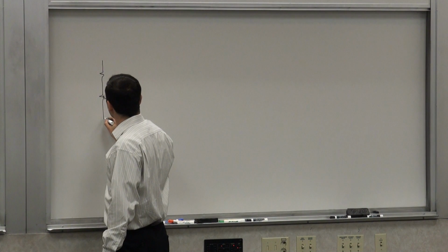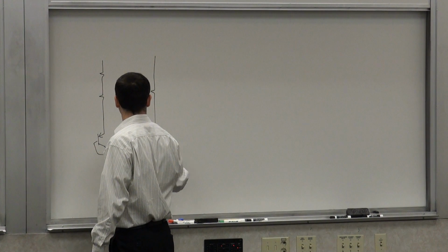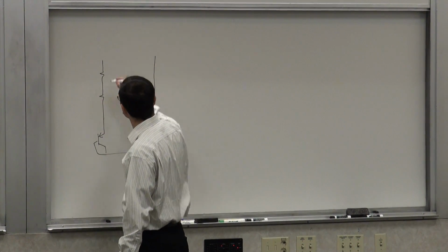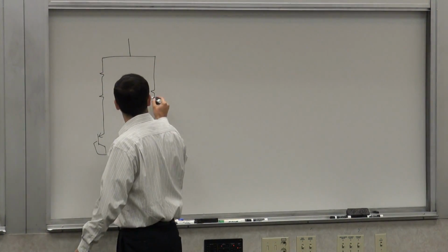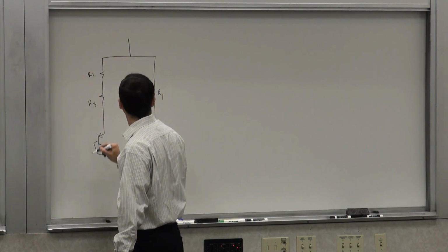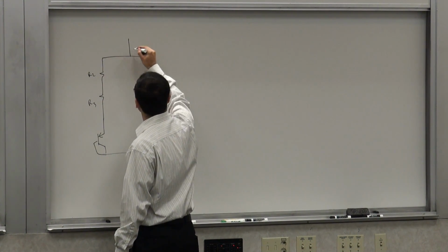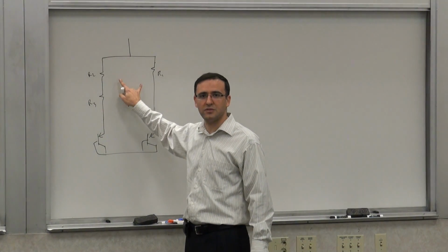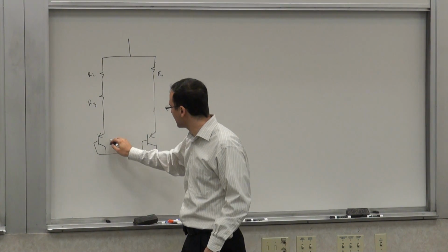So you take two VBEs and two resistors, connected transistors, and then you basically take this voltage. So let's call this R1, R2, and R3. And then I want to force these two voltages to be equal. This is another way of achieving that thing, right? Forcing these two being equal. But it doesn't necessarily force the current to be equal in this case. So these are both the same size, by the way.